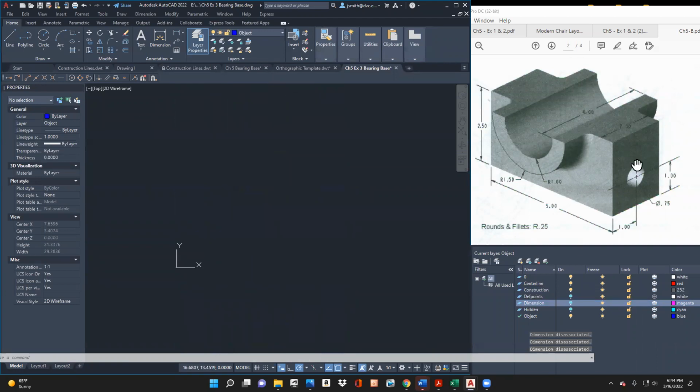So now I'll build this and I'll say this is going to be my front, obviously the top, and then I'll draw the right view here. Okay, so let's go ahead then and I'll go to my draw. I'm going to draw a construction line. It's going to be vertical. It's going to start at 0, 0, and then push enter. I could do the offset here. Let's just go ahead and draw the horizontal one. So horizontal, again, 0, 0, and that's that.